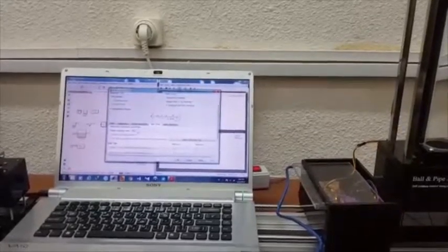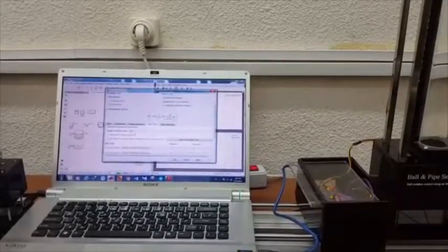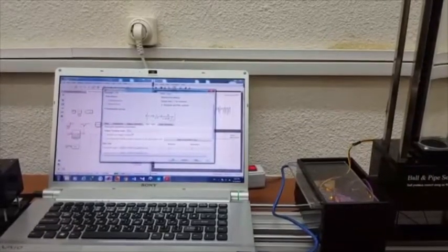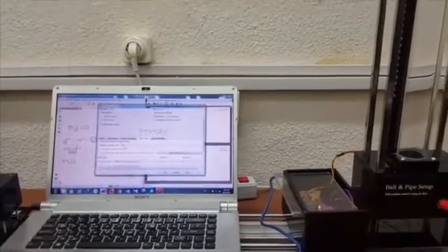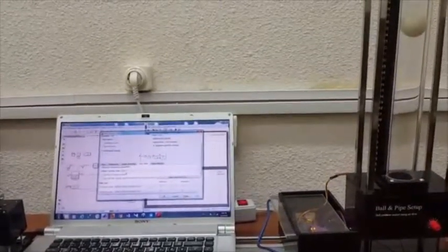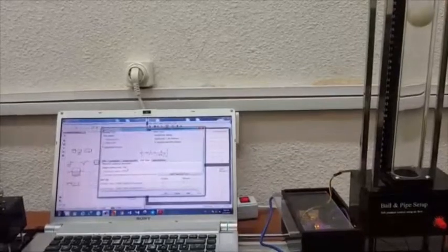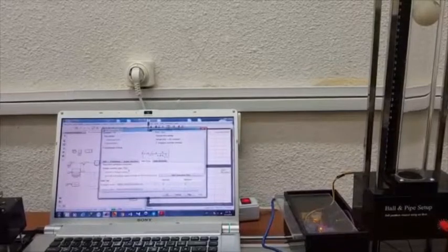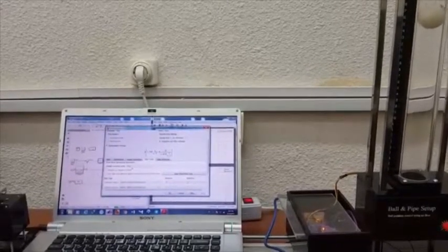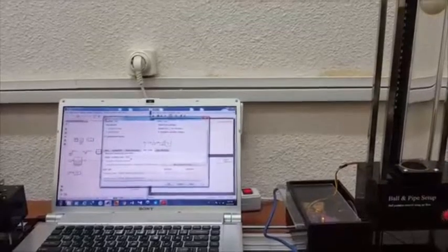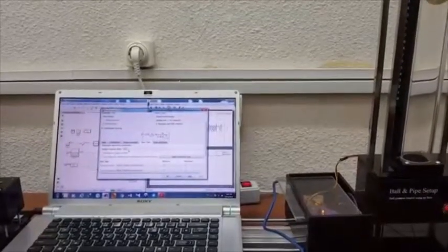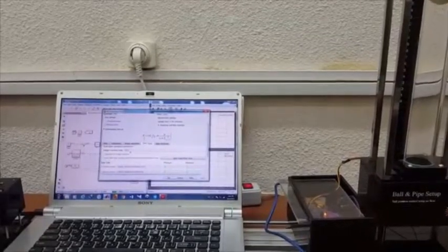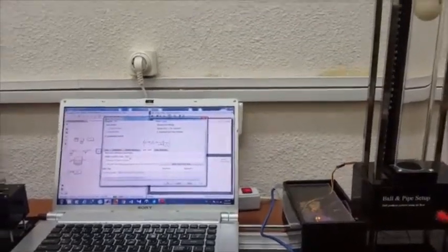For example, by decreasing the proportional gain, a slow response will yield, and of course, a better stability. And by increasing the P gain, fast response and instability is caused. Also, by increasing the integral term, it yields a decrease in the steady state error, but also can decrease the stability. But by decreasing the integral term, this can increase the steady state error.